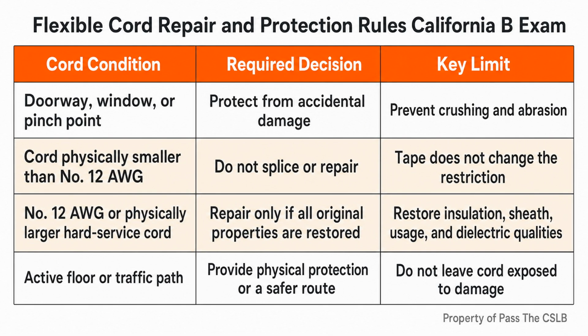This is a useful distinction during a site walk. For a grounded tool, I check the plug and cord for the grounding path and obvious damage. For a double-insulated tool, I look for the manufacturer's distinctive marking. I do not create a third category called probably fine.